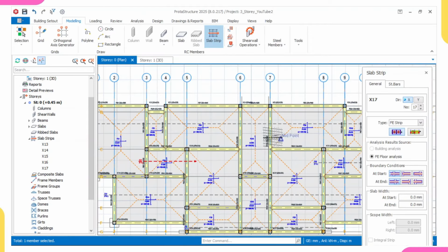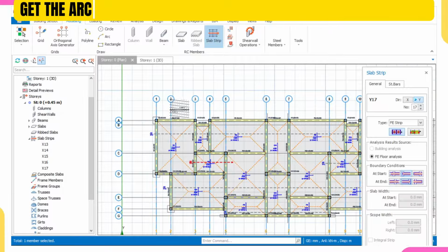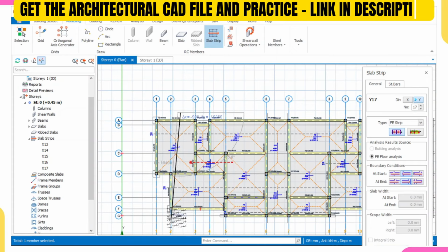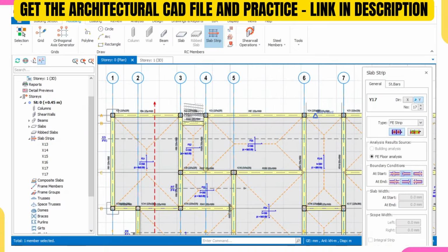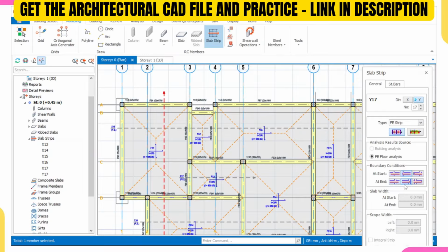So look at it. After this, the next thing is to do the vertical direction, that is the Y direction. I'll come over to this and click on my Y direction. So what is the boundary condition? I'll still pick these two things as my boundary condition. Then I'm having the slab to run from here. I'll hold my control key to straighten the line and click on this point. So coming over to this point now, remember we have designed for this slab, so we will stop here. That means this is our starting boundary condition, and this will be the ending.